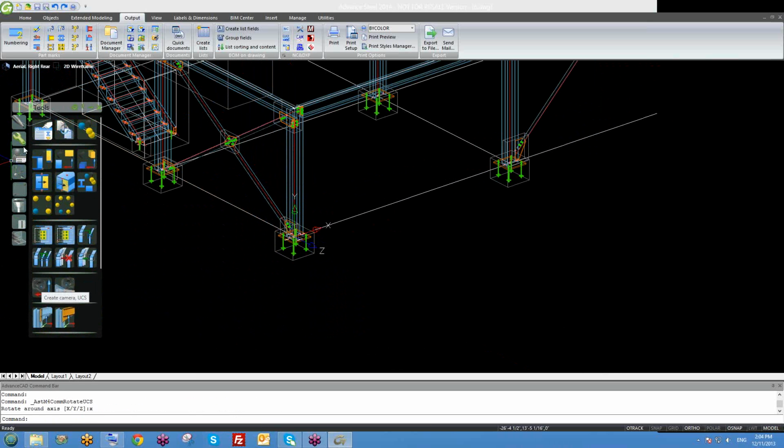All right. So camera. Go to the second tab. They changed a little bit the location of cameras in 2014. So I have these tools here. The next icon from the top. I pick this command here. Create camera. All right. We have 2 options. Create camera at UCS and create camera just at node. We're going to see this one, but at the moment we're going to work on this. All right. Select. Location point.